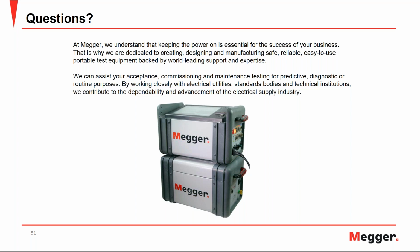We have actually written a paper on this, and we would be happy to share that paper where we explained why the power factor values turn negative. That is basically when the surface leakage current drives the phase angle between voltage and current greater than 90.